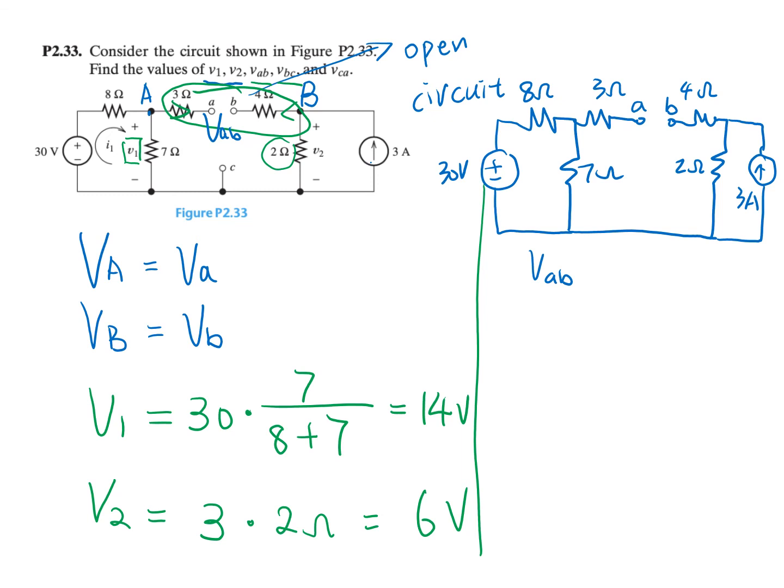And we can use a voltmeter method. So let's imagine this is connected to a voltmeter, V. With a voltmeter, the inner resistance is infinitely large, we can assume, and there is no current passing through here, and the voltage we measure is VAB. So we can write the KVL equation to express this relationship. That is